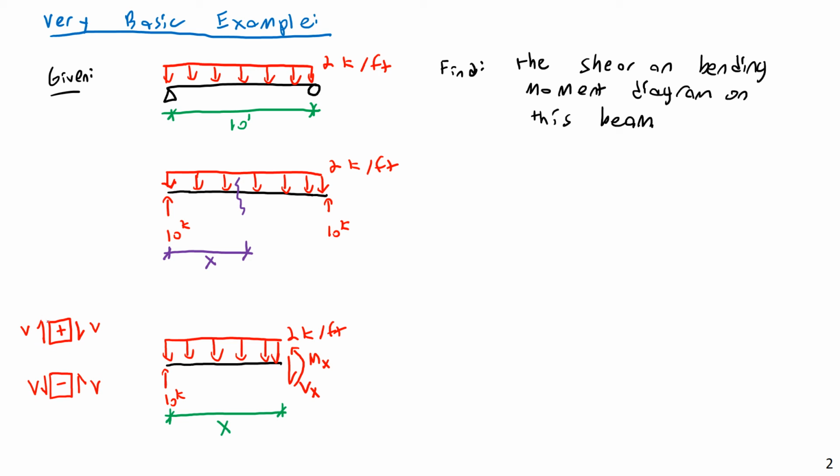Alternatively, another way you can think about it is if your shear arrows look like they're moving in a clockwise direction, that's positive shear. If they're moving in a counterclockwise direction, it's a negative shear. Or you can think of it as their sign conventions going a little bit opposite to moments.